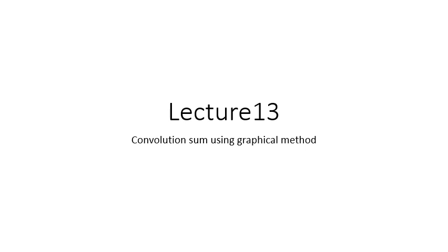Currently, you understand we are doing the convolution sum, right? So the next topic will be the convolution integral, right? And you understand we are doing it now using the graphical method. In the graphical method, we plot the two signals, that is the response signal and the input signal, and reflect one of them. It's up to you whether you reflect and shift the response signal, or you reflect and shift the input signal, right?